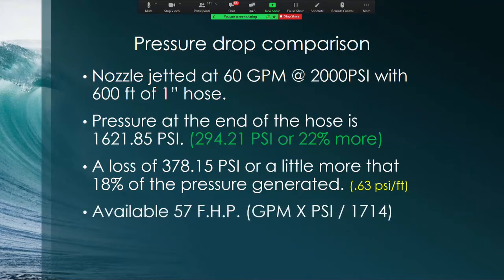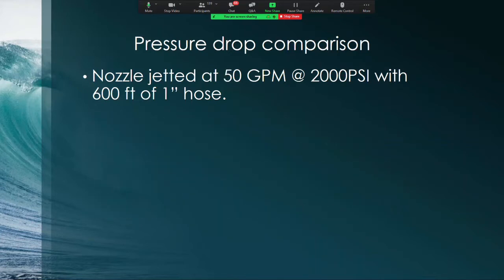Fluid horsepower ratings at this now, I've dropped the flow, so it's flow times pressure, but my pressure has come up. So my fluid horsepower rating at this setting is 57 fluid horsepower, which means that although I've dropped a bit, I've gained some advantage. I've taken my flow down by 20 gallons, and I've gained some advantage in pressure. I've lost a little bit of my fluid horsepower, but I can still provide a very good experience on cleaning.